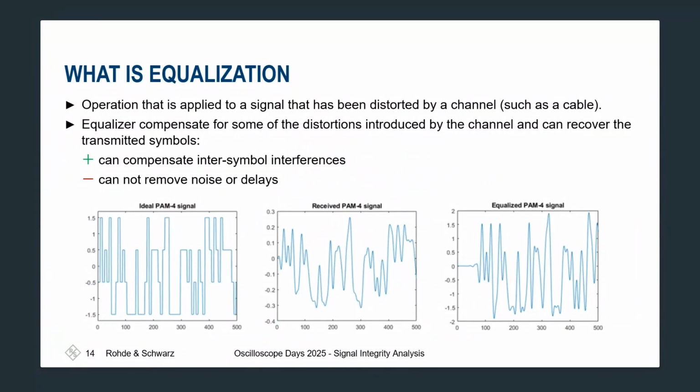And then if we look a little bit further into equalization as well, this is typically a way to combat what we call intersymbol interference. So this is when you might have quick transitions from ones and zeros, and essentially because of these quick transitions, they can then cause it not to quite get to the level of 0 or not quite to get to the level 1 and can cause distortions. And so this is what we're seeing here.